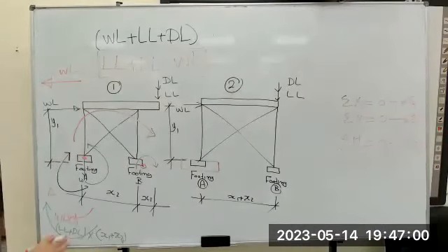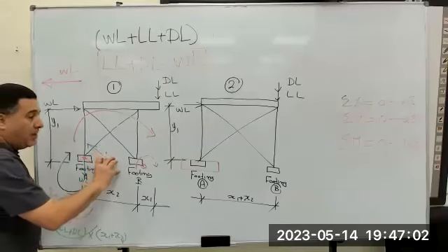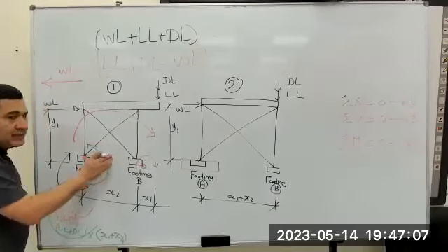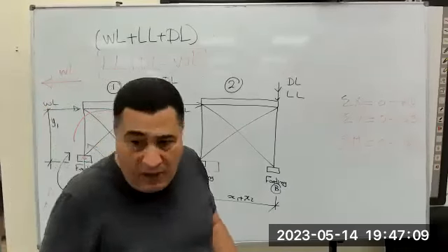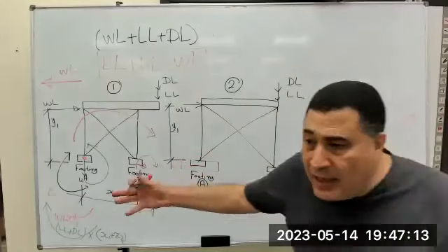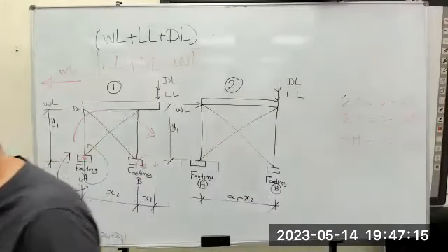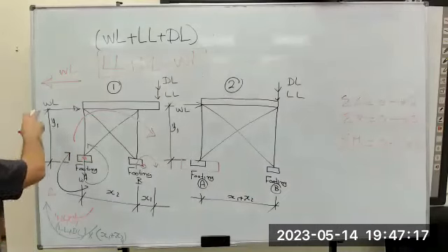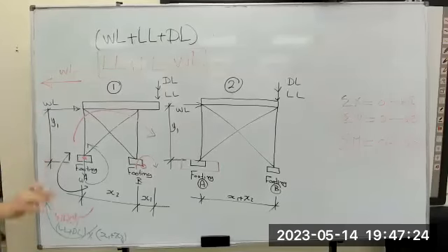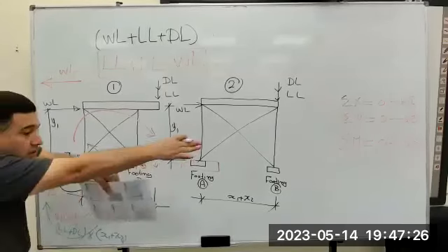If the summation of the forces here or the moment is not 0, it means what? Sure, 100% this system will fail: overturning, uplifting, sliding, whatever. If the wind load is too much and there is no overturning and no uplifting, the system could slide.